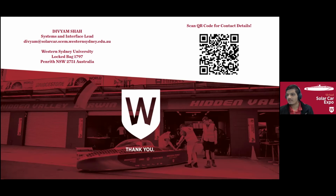We're able to test all of our settings for similar analysis on that plate, see what results we get through FEA, and then test that plate to destruction, and see if the results match up. That way we can make changes to our settings and calibrate it to be as accurate as possible, so that we can get as close to real world as possible.